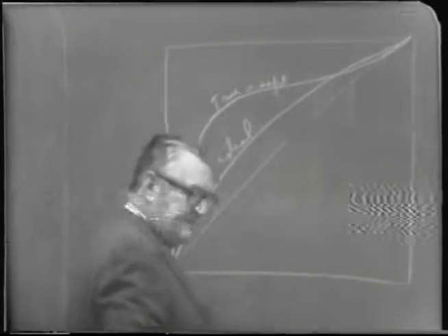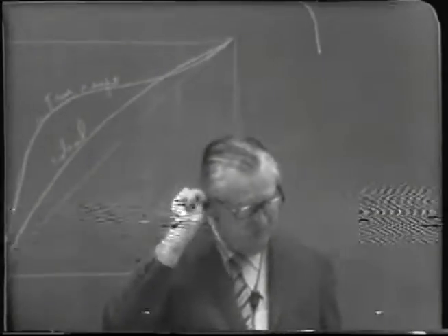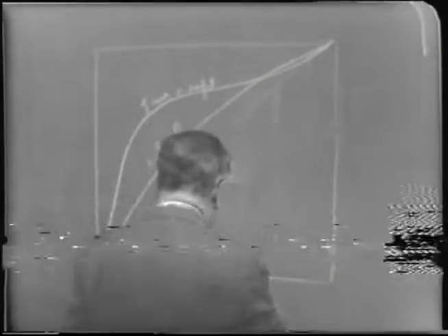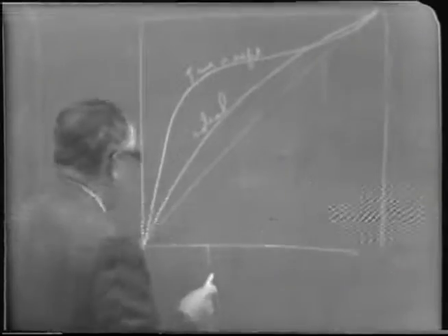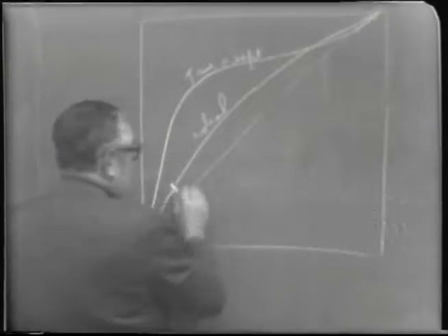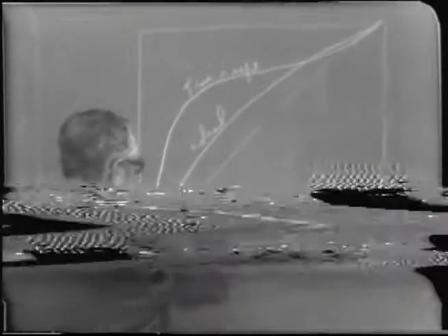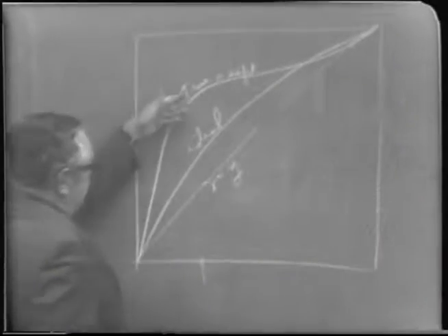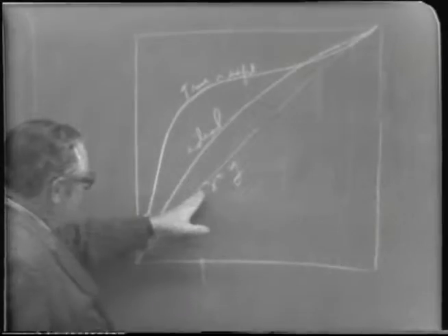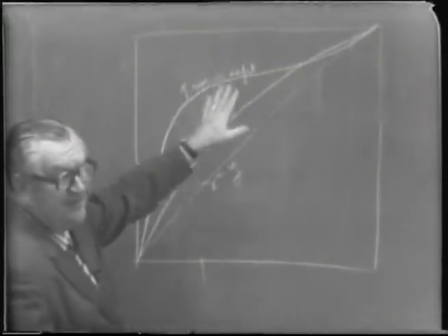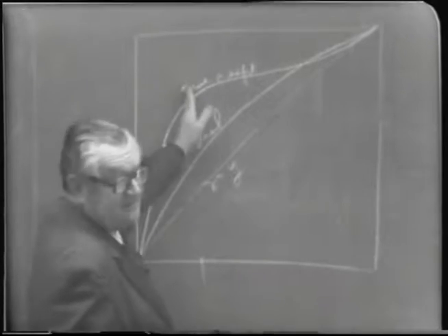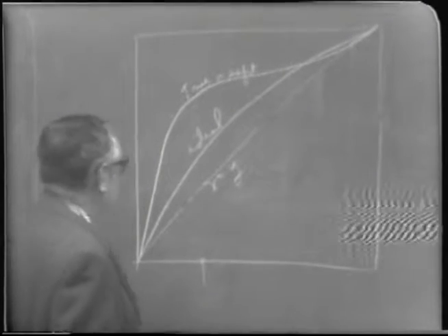Then I asked you to compare or discuss the relative ease of separation for an actual mixture of, if it was 25 mole percent, which is over about here, compared to what it would be for an ideal mixture. And so since the distance away from the equilibrium here, from the diagonal where x is equal to y, is sort of an indication of the volatility, or it is directly a measure of the volatility for a particular mixture.